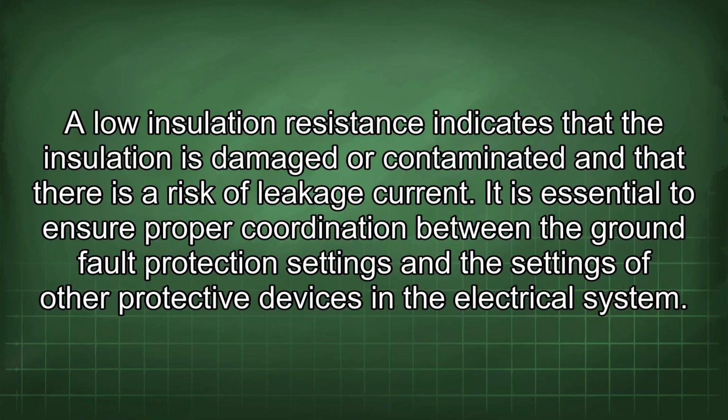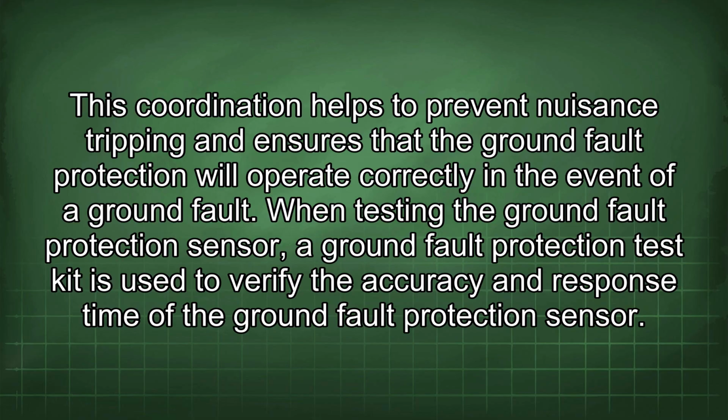It is essential to ensure proper coordination between the ground fault protection settings and the settings of other protective devices in the electrical system. This coordination helps to prevent nuisance tripping and ensures that the ground fault protection will operate correctly in the event of a ground fault.